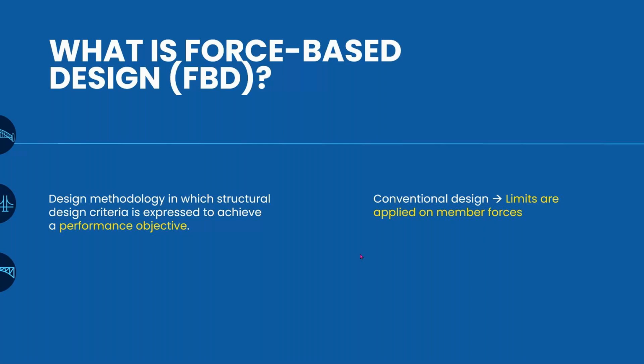And that is the reason why the problem that we are facing is we cannot assess what the structural state would be after a seismic event, whether it will be collapsed, whether it will be serviceable, or whether it will develop cracks. We do not know when we use the force-based design. And that's the reason we shifted to the performance-based design approach.